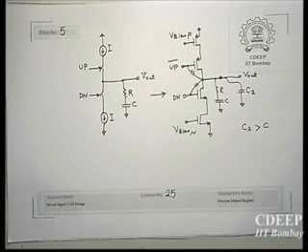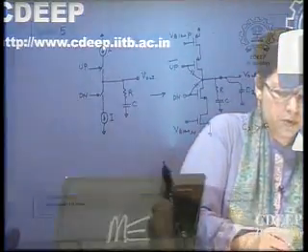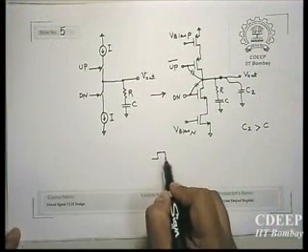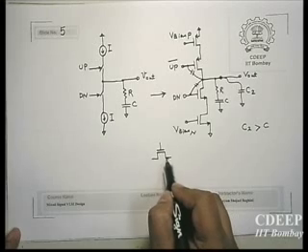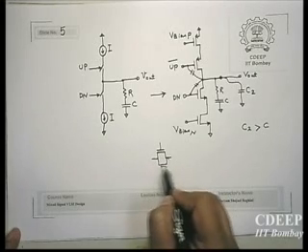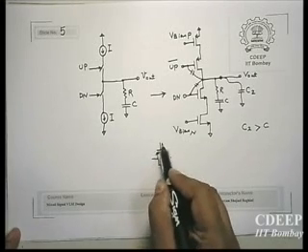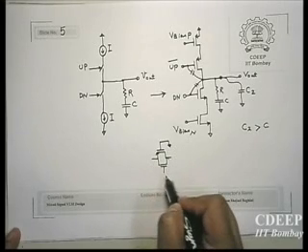And another problem is that because now you have up bar and down, you have one inverter delay, for example, at least between up and up bar, but you don't have it between down and down. Therefore it's better to add a dummy switch, or a dummy transmission gate, which will have the same delay as one inverter. For example, this is always on.